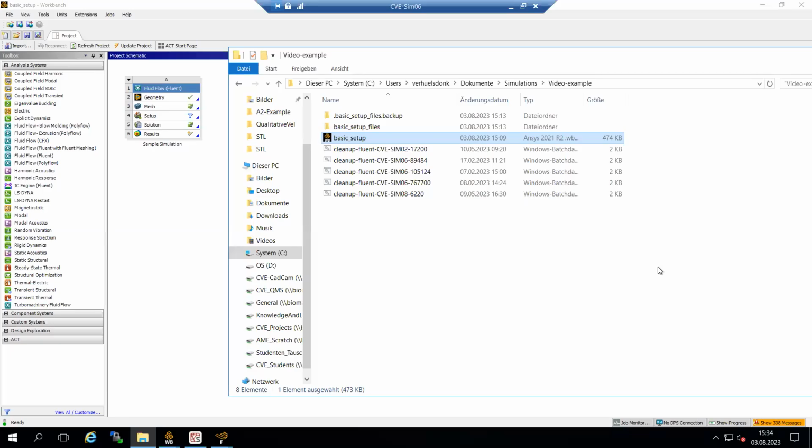Hello everyone, today I'm going to show you how to use the moving mesh method to simulate a ventricle in ANSYS Fluent. For that we have provided a project file in the repository where you can either use the given geometries for the ventricle or use your own. If you have UCD data, then you should use the provided MATLAB script to convert them to STL. If you have your STL files, you can put them in this.